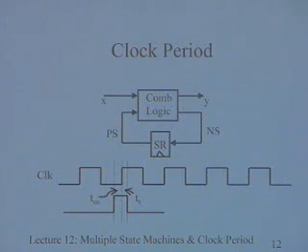So basically what it means is, once I have made my design, can I say at what clock frequency I will operate it? Of course, the problem could also be specified differently. You could say: do a design which should work at 10 megahertz. I am not immediately looking into that problem, though I will give you some hints on how to go about it. Here I am looking at the reverse problem. I made the design, and can I analyze and say up to what frequency it will work, what is the maximum frequency this particular design will work at.